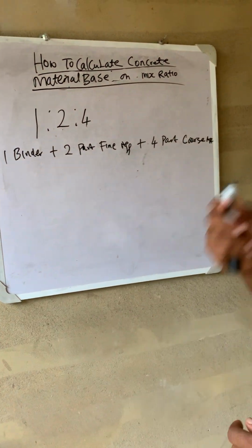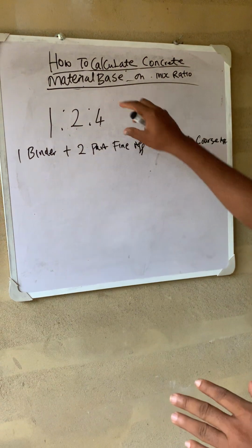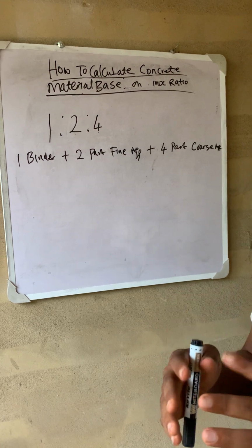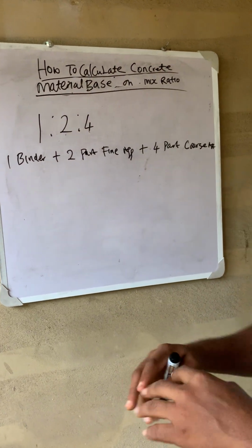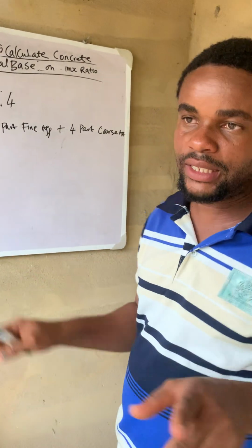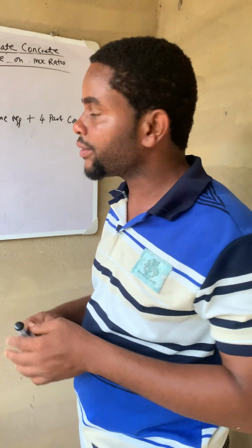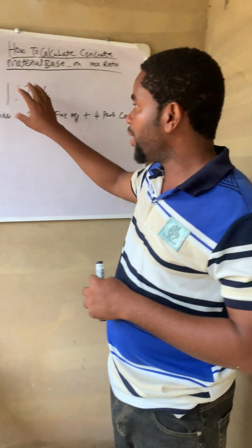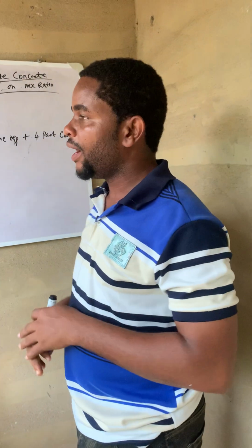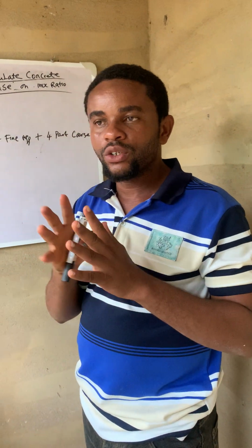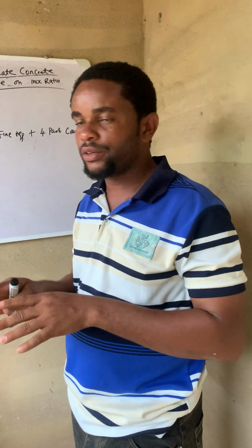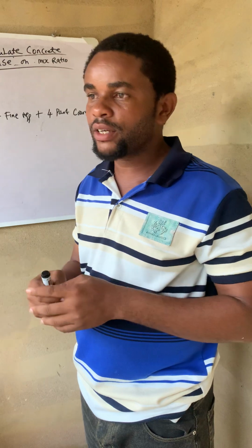Alright, so remember, we have different types of cement storage, but what we use in normal day, maybe in a local concreting, is cement in bags, and cement in bag weighs 50 kg, 50 plus or minus, but let's take it 50 kg, and then 50 kg is equal to 2 headpan of cement. You can do that on your site.